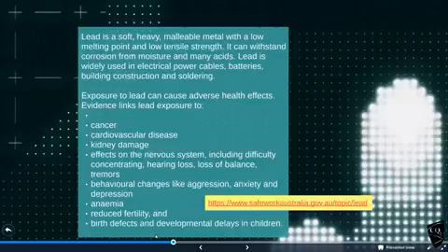It's unaffected by lots of acids and chemicals. It's widely used for heavy-duty electrical cables, in batteries, in building construction, and it can be used as a solder as well. You'll find it's mostly used on things like roofs. They used to line water tanks with them. The Romans used lead as water pipes, both of which are not good ideas really, because it's not that good for you if you ingest it.